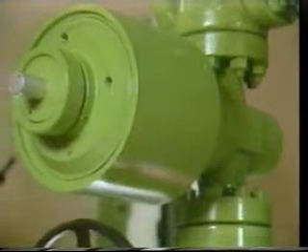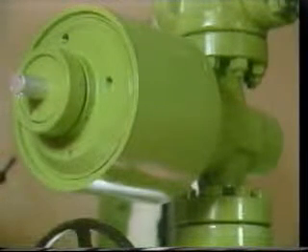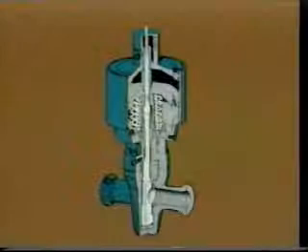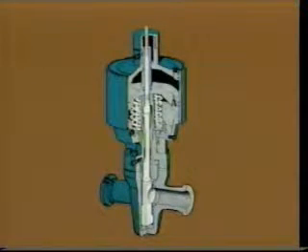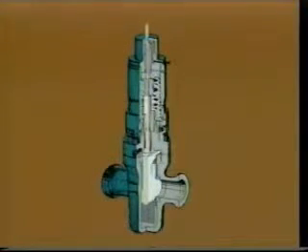and opens or closes the gate valve using either compressed air or pressurized hydraulic fluid. The compressed gas or pneumatic actuator utilizes compressed air or produced gas to operate the valve. This gas pressure is applied to the piston, holding it down into the open position. A spring closes the valve if pressure falls below a predetermined value. Hydraulic valves differ mainly in that hydraulic fluid is used to move the piston. They are more commonly used when the actuator and subsurface safety valve are both controlled by the same system.